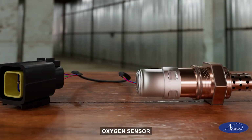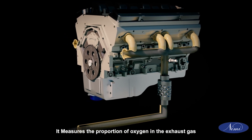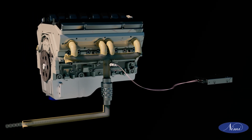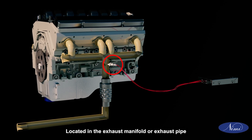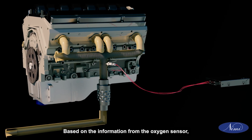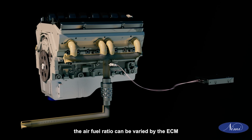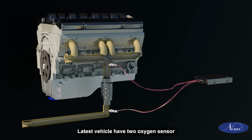Oxygen sensor. It measures the proportion of oxygen in the exhaust gas. It sends a signal to the ECM. It is located in the exhaust manifold or exhaust pipe. Based on the information from the oxygen sensor, the air-fuel ratio can be varied by the ECM. Latest vehicles have two oxygen sensors, on both sides of the catalytic converter.